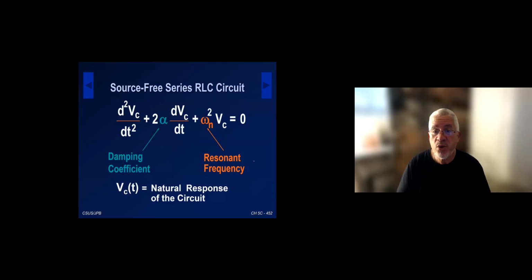So this will be the standard form of differential equation that we're going to solve. The only 2 cases we're concerned with in this particular section are the case where it's equal to 0, in the case of a source-free circuit, and later on, equal to a constant. Other than that, we're not doing the more advanced types of solutions, the more sophisticated differential equations that you had seen in your differential equations course.